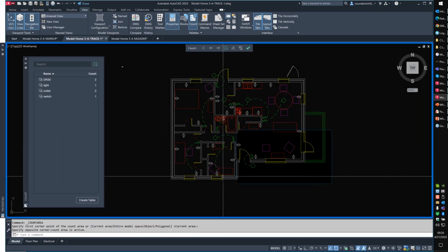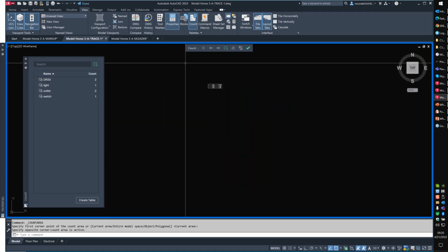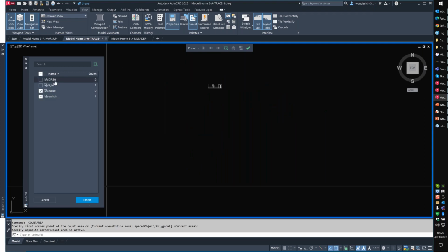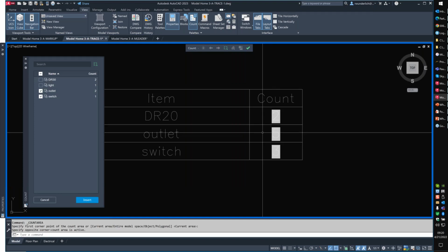So that becomes that. Make sure that that did not update. See, it automatically sees we already have the switches and outlets. So that does not work. You would need to explode the table if you need that based on what you need, or you draw a closed boundary that does not intersect itself, does not cross over itself with a polyline, and you can use that.